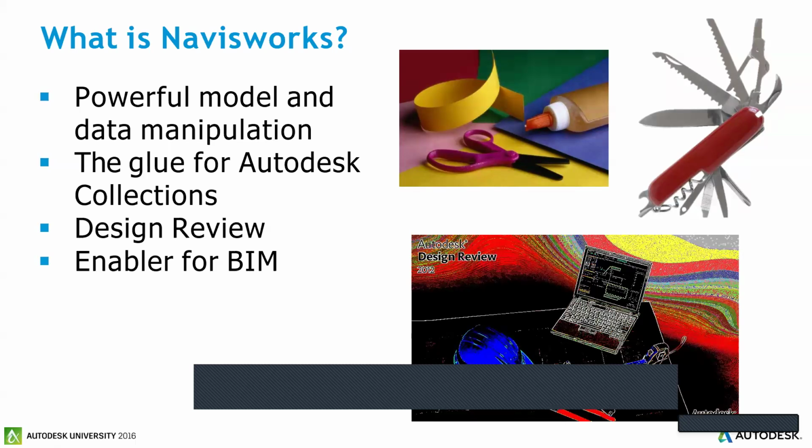Then you can take those particular IDs, copy them, paste them onto the Revit part, and resolve these issues depending on who has made the mistake. It depends on those things, and it needs to be prioritized, right? The integrated model is there, and then you need to prioritize what the problem is, as well as who is going to resolve that particular problem in his own model.